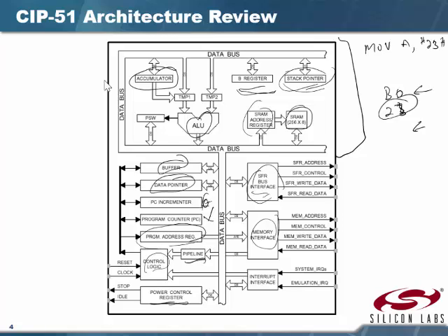That makes this processor a little different from a standard 8051. We've got the memory on the chip, so we don't have to add to it or do any wiring to it, but we have to treat it in software as if it's outside the chip, and that's very easy to do.